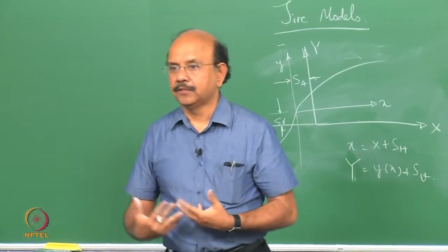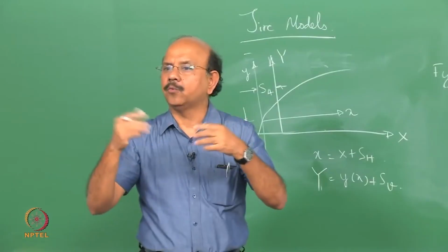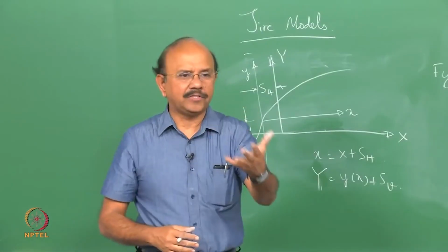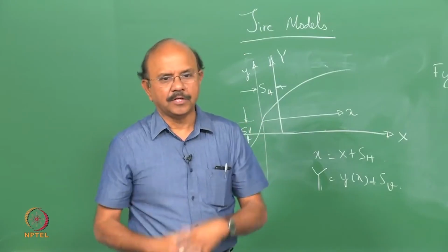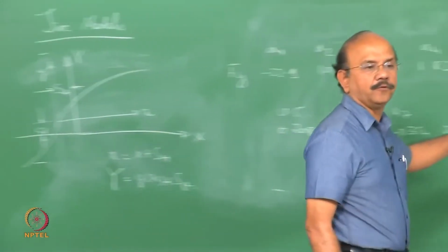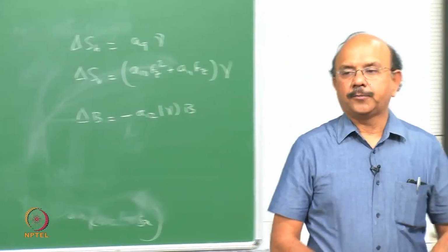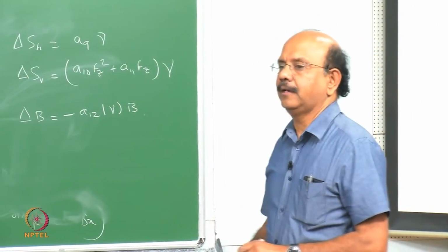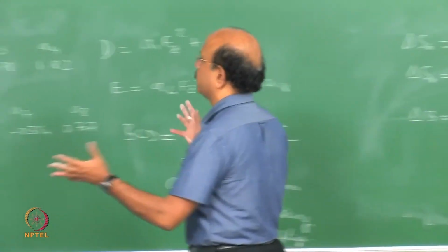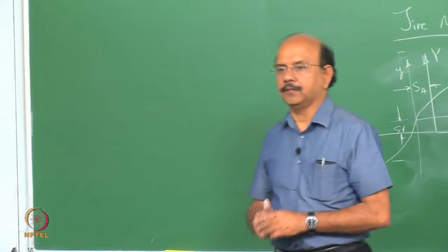So what do you get? I get a curve, not one curve. I have to change FZ, and I'll get a series of curves. I have to change gamma, and I'll get a series of curves. So with all these curves, now I have to fit A1 to A13. There are special softwares available for it, and there's quite an amount of research too. It's an optimization problem that can be used in order to fit A1 to A13.